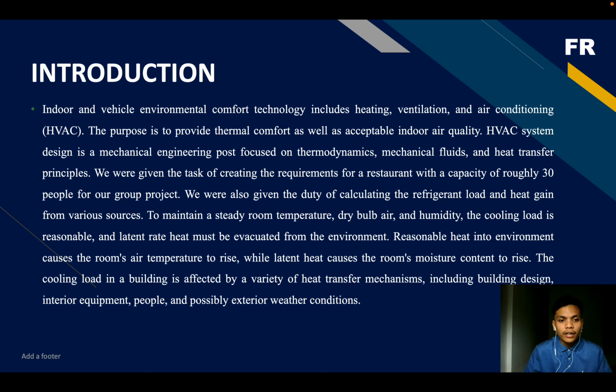Sensible heat into the environment causes the room air temperature to rise, while latent heat causes the room moisture content to rise. The cooling load in the building is affected by a variety of heat transfer mechanisms, including building design, interior equipment, people, and possibly exterior weather conditions.